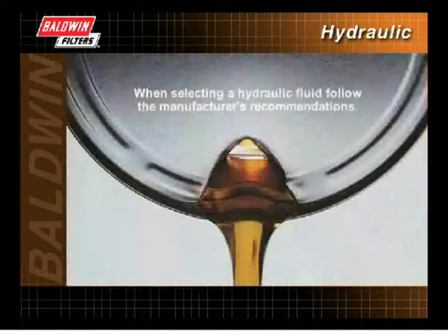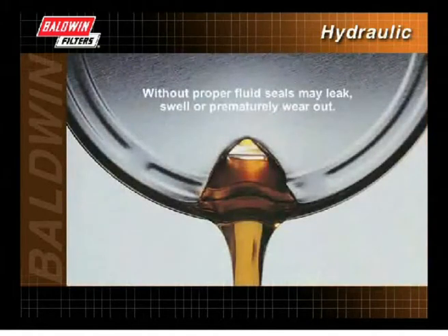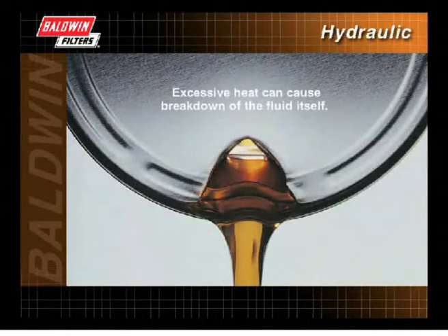The manufacturer has designed the equipment to a certain fluid performance level. Without proper fluid, seals may leak, swell, or prematurely wear out. This can generate heat, causing the fluid to overheat and may allow entry of contaminants into the system. Excessive heat can cause breakdown of the fluid itself.